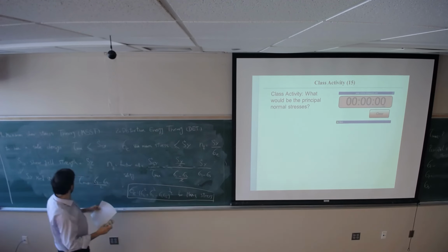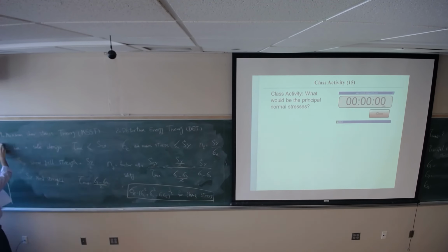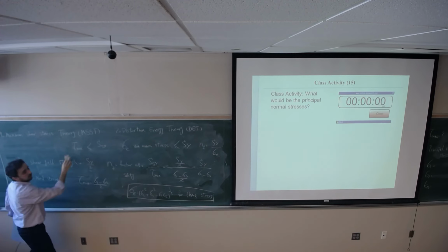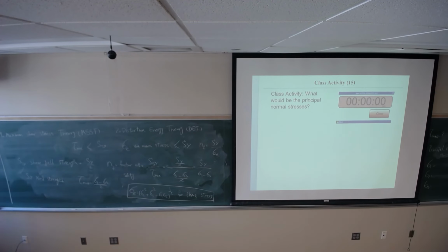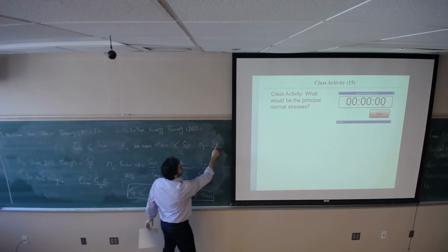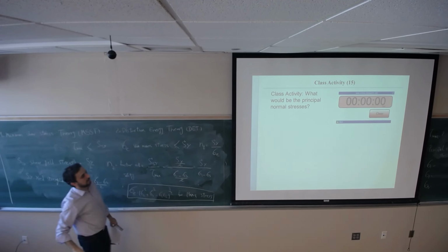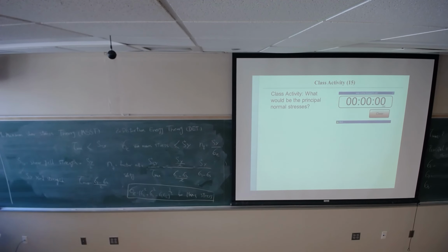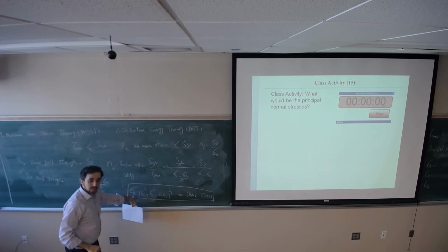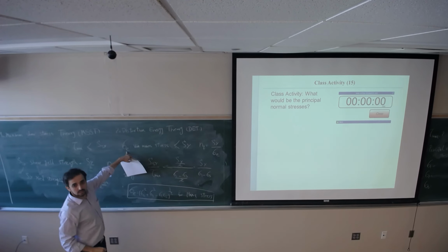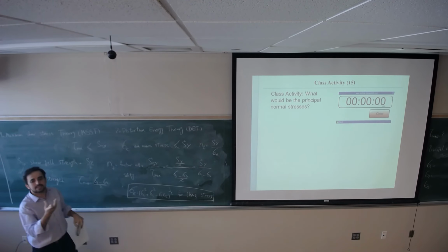So let me take a question about this. Yes. The safety factor for DET is SX or SY? This is SY, the yield strength. And it's coming from the properties of the material. Yes. Could you just tell me what word came after sigma zero? Which one, this one? No, sorry, the word that you used to explain what it was. Yeah, von Mises.